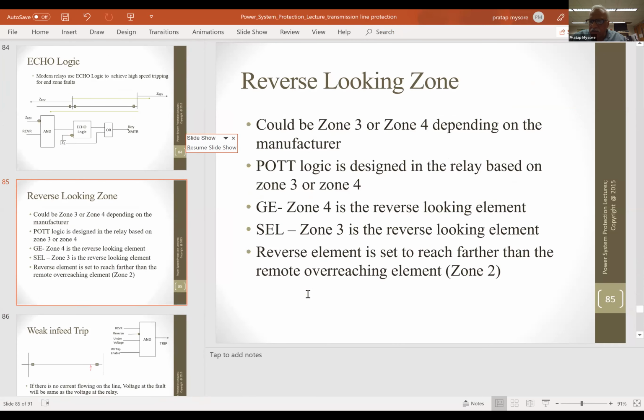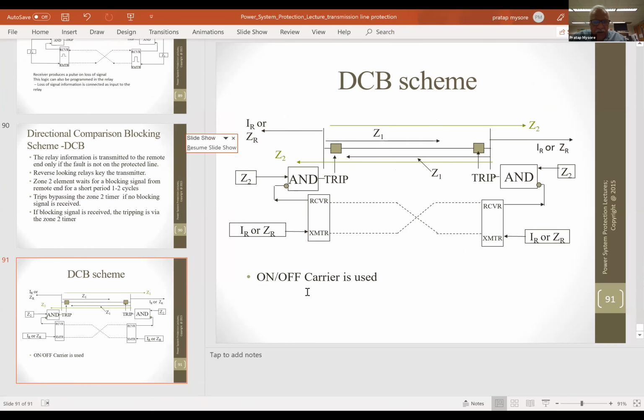So what we covered today after the break was transmission line protection. We went through the concepts of transmission line distance protection. We already looked at current differential schemes where they exchange information of the current. Then we looked at the ratio of calculating the impedance up to the fault point by dividing the voltage by the current. And then we found out that we need to use the faulted voltage as the voltage input, and the currents depend on the type of the fault.